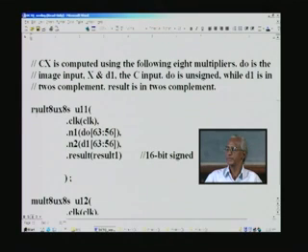So this is the first of the set of multipliers numbered U11 through U18, that is 8 multipliers, and at each step this one will be the X matrix, and notice that only 1 byte is covered by one multiplier, and the corresponding C value is available here. Once again the corresponding byte is taken in order to process, and it produces a result called result 1, and this is 16 bit because it is 8 unsigned into 8 signed.